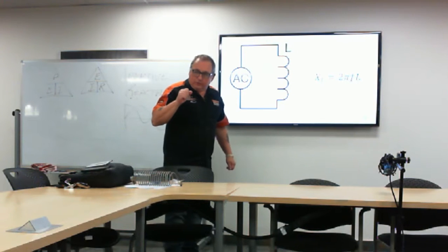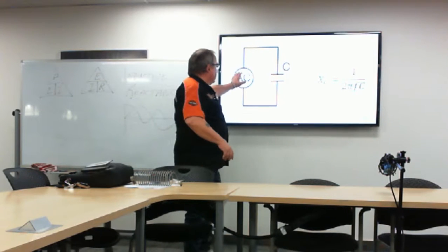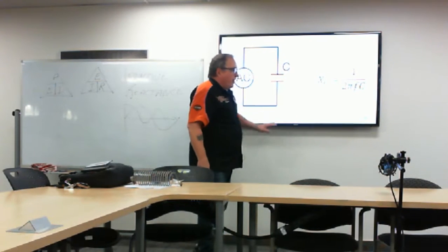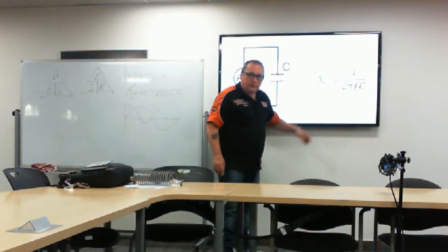Now show me the next one. I'm going to zip through this and then it'll become clear. This is a capacitor. A capacitor has capacitance, but it also has capacitive reactance. I neglected to tell you, in a capacitor, the current leads the voltage. And this is very important. If you put DC on a capacitor, it's like a dead short. Zoom, that current goes in there. So when you do the AC part, it's ahead of the voltage.